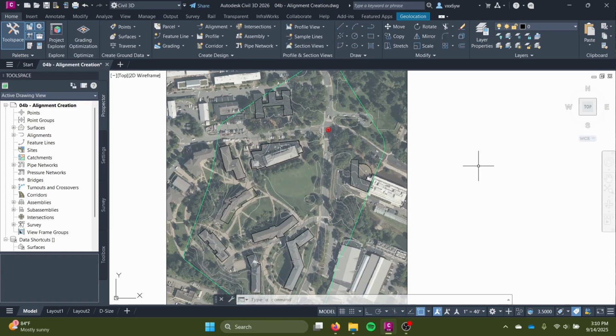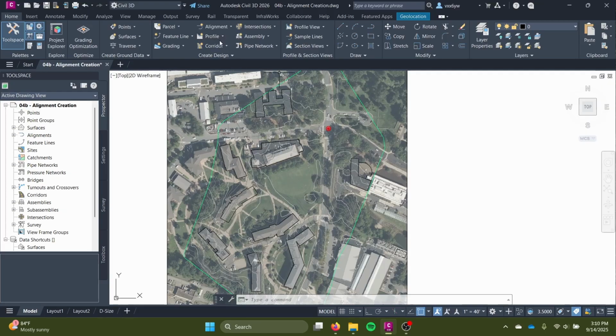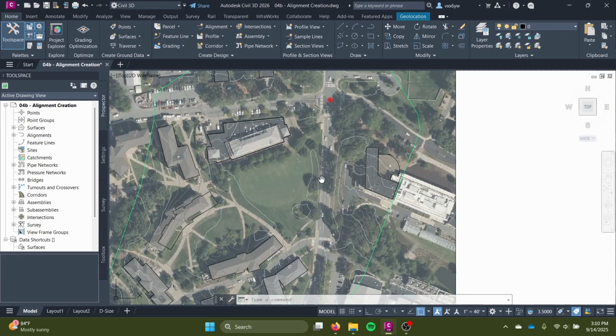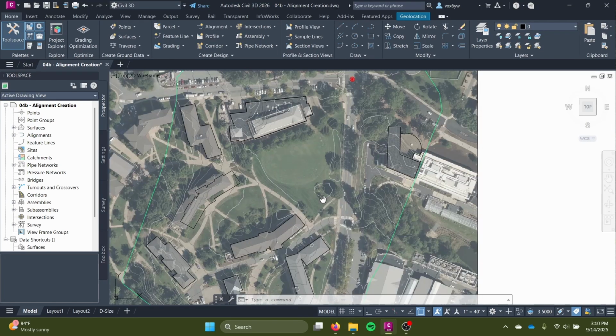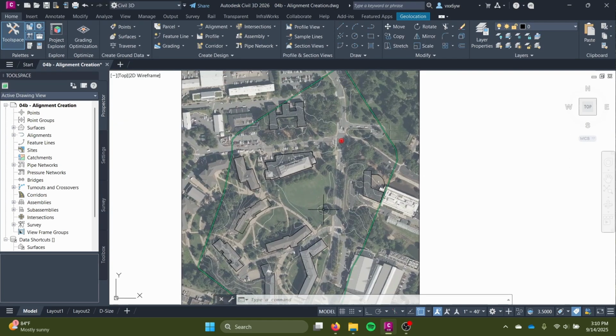So they show the northing and the easting of your design, or you can call it the X and the Y, for example, the north, south, east, west plane, whereas profiles will show the elevation, the up and down of your design. Another good analogy to think about is that alignments are akin to your plan views. Profiles are similar to your profile views. And when we get to the assembly, that tool is like your section views. So we're going to do all of those, and we're going to do them by modeling McCormick, Alderman, and Treehouse Drive.